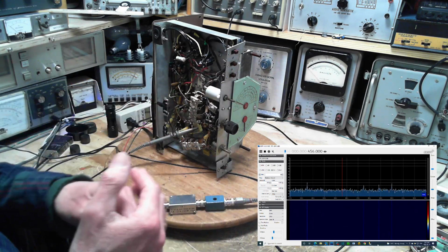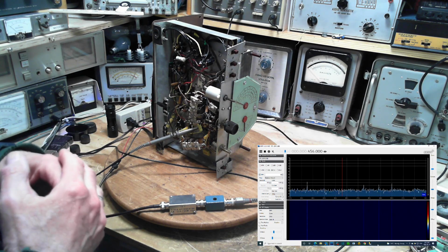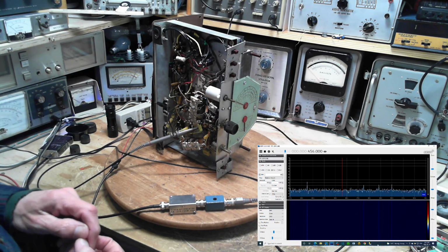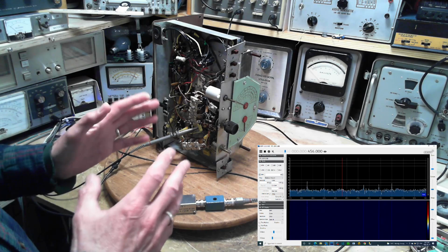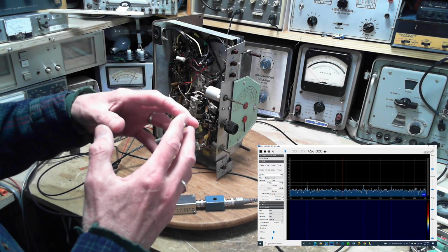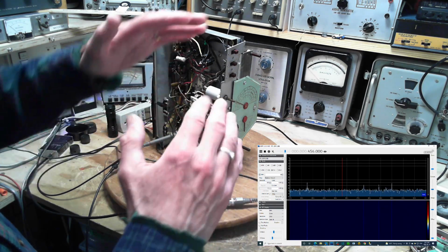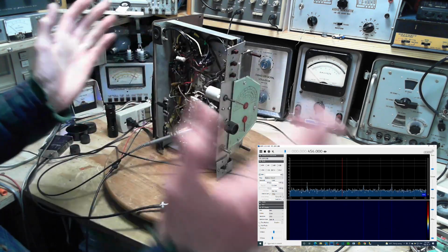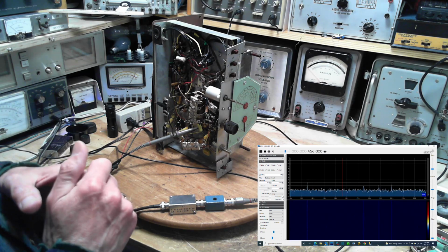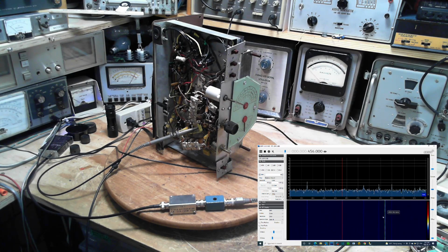Now what if it's not 455? What if it's 600 coming out? I said that wrong. So if there's a 600 kilohertz signal coming out of the mixer tube, what it's looking at is a low resistance. And so it should be weakened. It should be suppressed. In fact, if it's far enough away from 455, it should be pretty much wiped out, I would think. Far enough away being a decade away? I don't know. Let's try it and see.